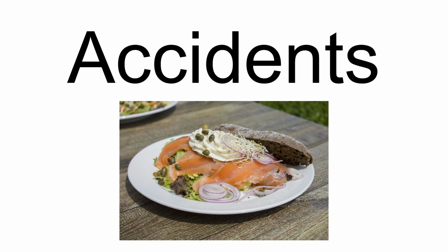On October 19, 1959, a Boeing 707 on a customer acceptance flight, where the yaw damper was turned off to familiarize the new pilots with flying techniques, a trainee pilot's actions violently exacerbated the Dutch roll motion and caused 3 of the 4 engines to be torn from the wings. The plane, a brand new 707-227, destined for Braniff, crash landed on a riverbed north of Seattle at Arlington, Washington, killing 4 of the 8 occupants.